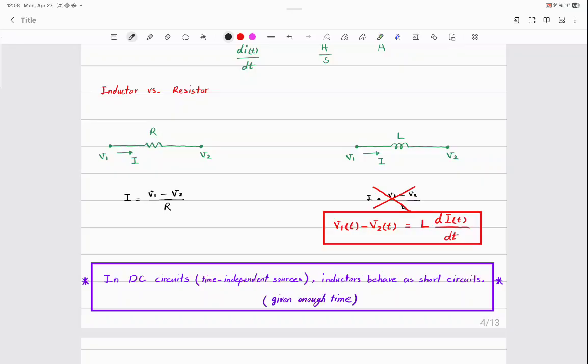If there is a switch in the circuit, in a DC circuit, we usually need another condition in order to be able to consider the inductor as a short circuit. Yeah, it should have been in that position for a long time. Well, let me put it this way. Technically, saying DC actually has that definition embedded inside of it, because when I'm talking about a DC circuit, I mean nothing changes.